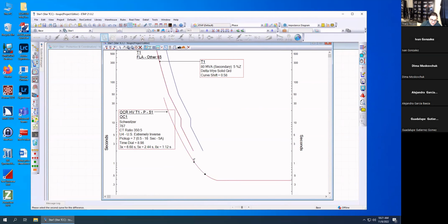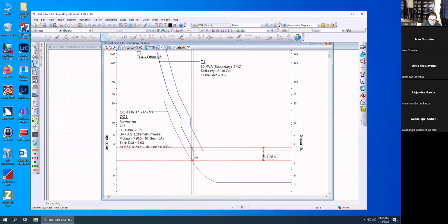Then let's select the actual overcurrent curve, and you'll have this little bar. You can slide it around and see the time frames, and you can see delta T. We want to go all the way to the very bottom, and then we have 0.86 seconds. I want to move this around until we get about 1 second, so let's move this a little closer. I might have to update a little bit. 0.5. You play around with it. 0.75, that's probably good enough.